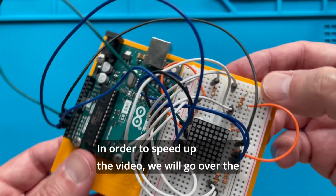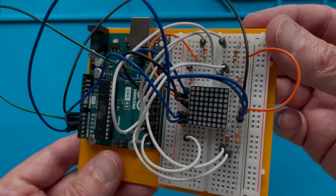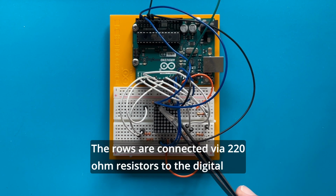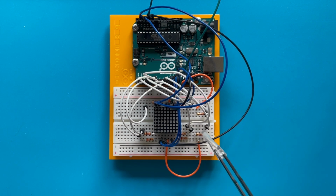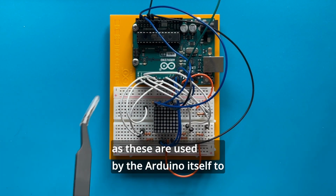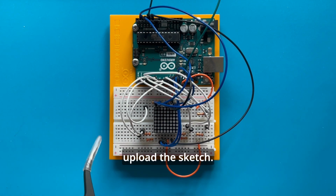In order to speed up the video, we will go over the different components step by step. The center of the project is the 8x8 display. The rows are connected via 220 ohm resistors to the digital pins 2 through 9. We do not recommend the use of the digital pins 0 and 1, as these are used by the Arduino itself to upload the sketch.